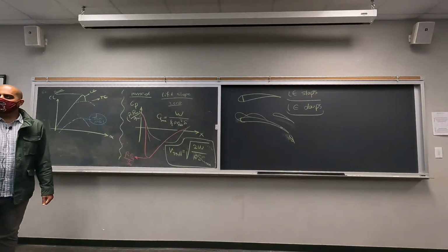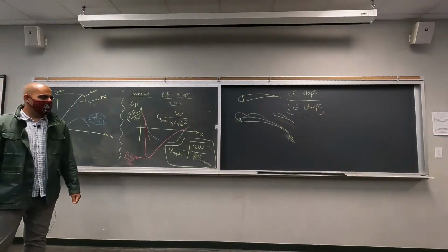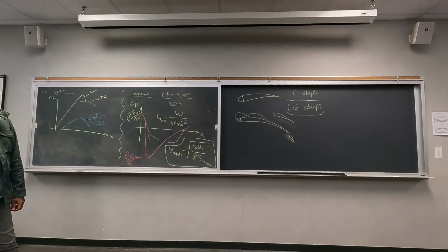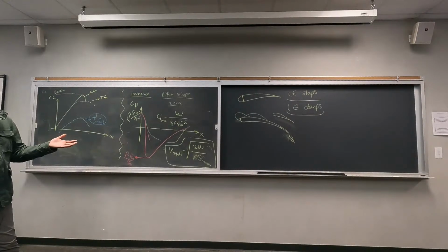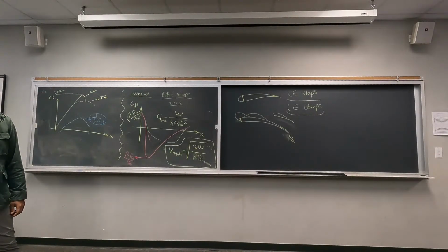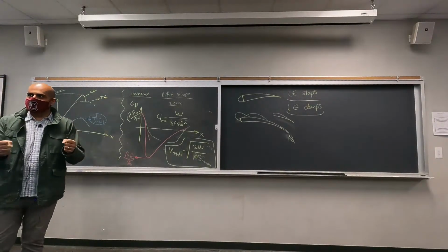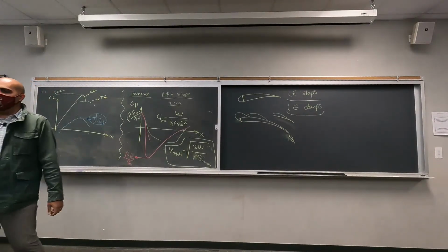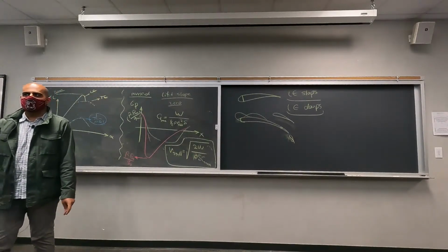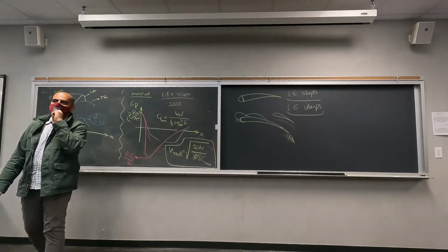I feel like we still have to do something with the chord length, try to change that somehow. Chord length. Yeah. So whatever we do is going to change the chord length anyways, right? Because increasing the camber is like stretching the airfoil, right? But think about it this way, how would stretching the airfoil change the flow pattern? How would that reduce the flow separation?